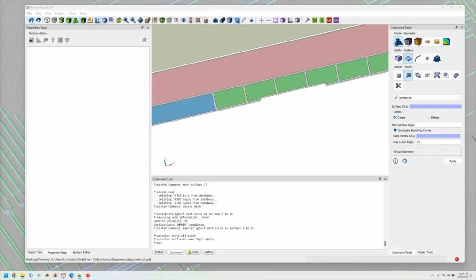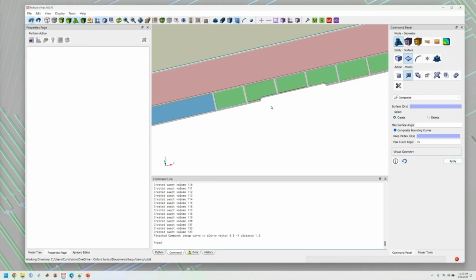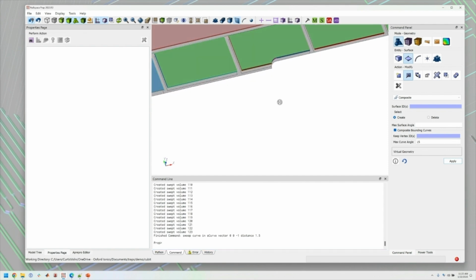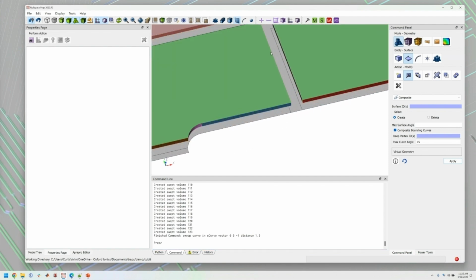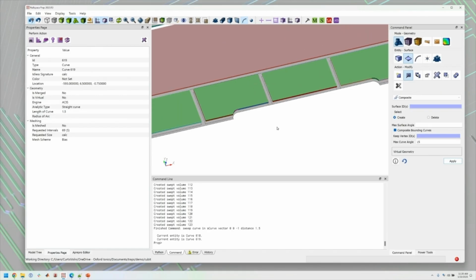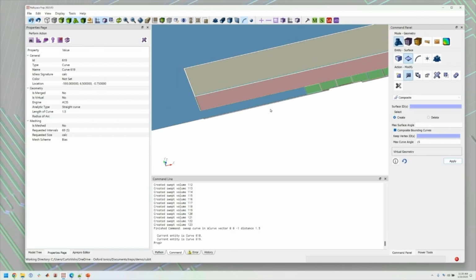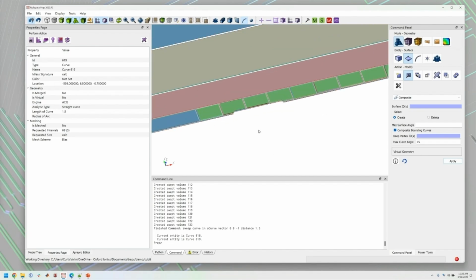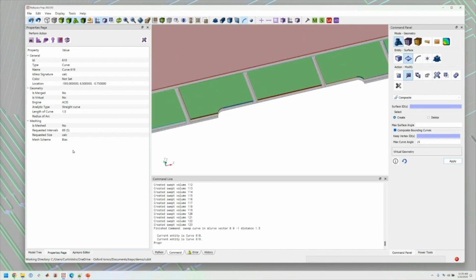Next thing to do is sweep all of the curves to emulate the thickness of the metal. So now we've added a 1.5 micron thick sidewall to all of our top metal electrodes, or at least the electrodes that are close to the ion again. So for instance, out here, we didn't put sidewalls on these electrodes because they're so far away that they simply will have no effect on the fields that the ions see here.